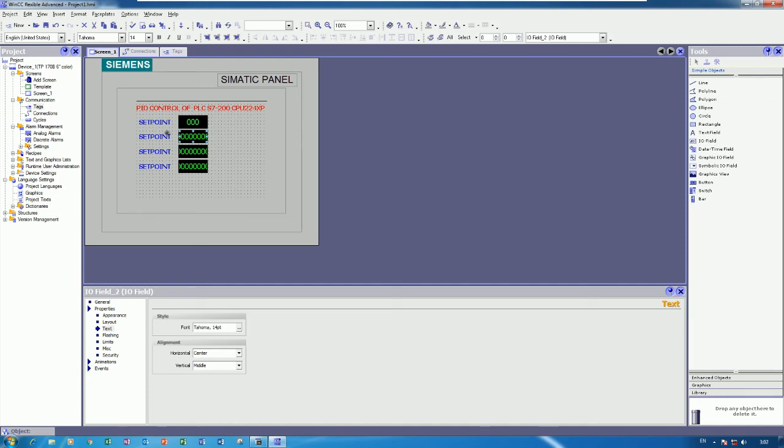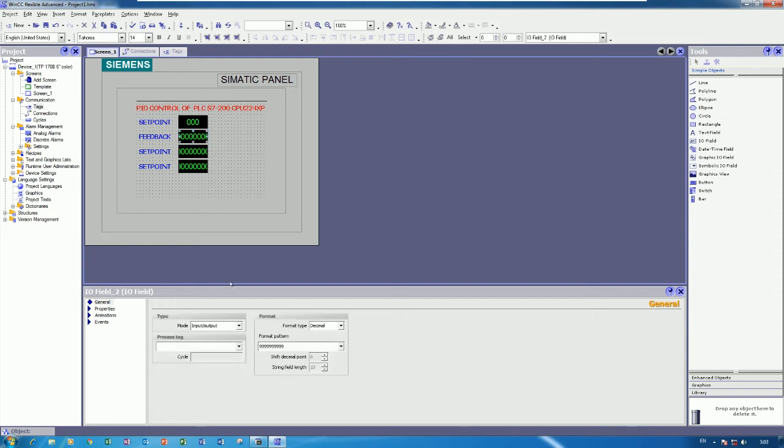And the second one is the PB, right? So PB, or we can say feedback. Okay, feedback. So feedback is the output, right? Input from instrument. So PB, yes. And like this also. So PB we need to scale, right? From 32,000 to 100, right?